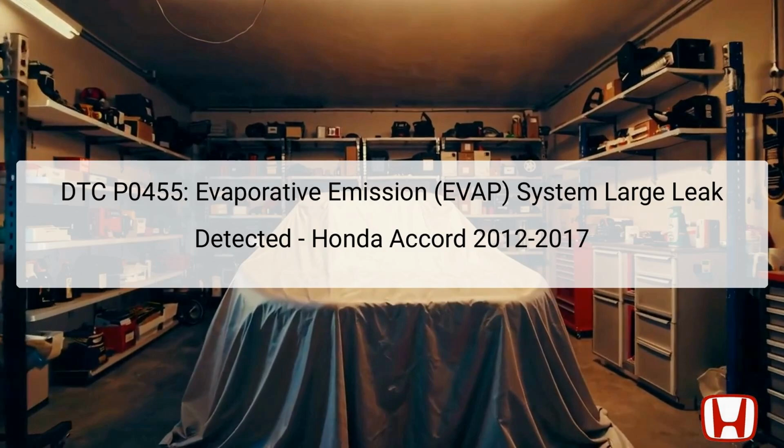DTC P0455 indicates a significant leak in the Evaporative emission system of the Honda Accord, specifically in model years 2012 to 2017. The EVAP system is designed to prevent fuel vapors from escaping into the atmosphere, which is critical for reducing environmental pollution. It utilizes an engine-off natural vacuum (EONV) method to detect leaks.